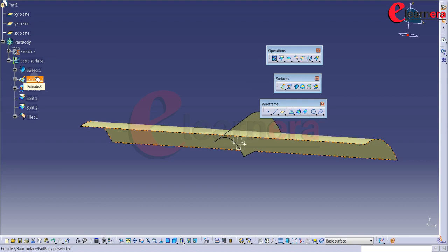What are the disadvantages of using OGS? Elements in this set cannot be shuffled irrespective of their sequence of creation, which is possible in geometrical set. The parent in this set is absorbed by performing an operation.